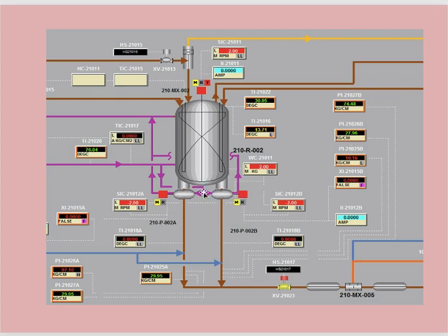There is a weight feeder, which is a weight sensing element to control the residence time inside the reactor. There is a coil, this coil to adjust the temperature of the reactor here, and there is a baffle to make good mixing inside the reactor between the reactants. So what I want to tell you is that it is not so easy as you think, the continuous stirred tank reactor. We need to study the main items composing this type of reactor.